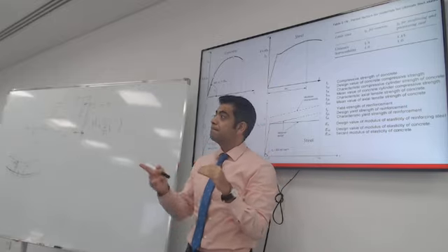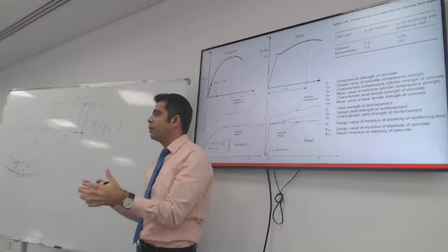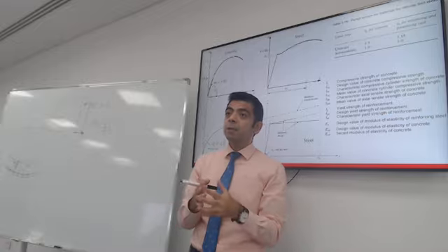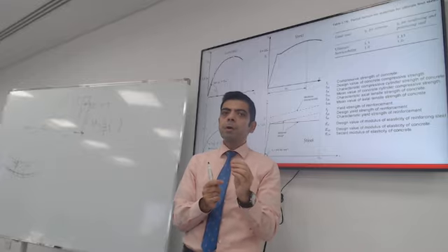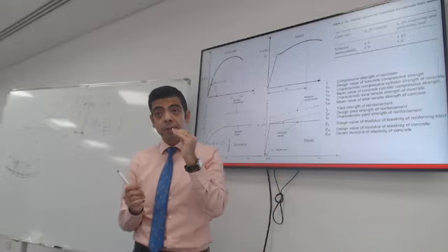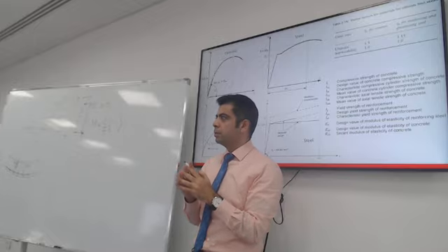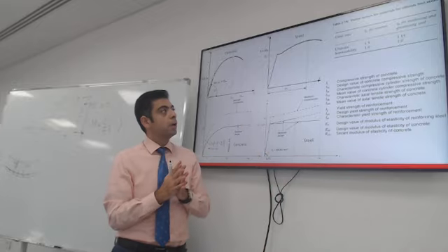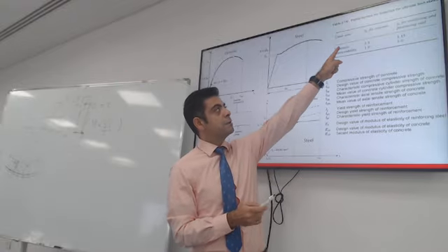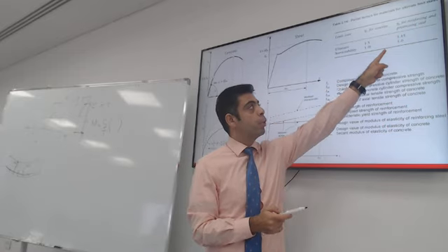Variation in manufacturing. Because concrete is manufactured mostly on site or in a concrete mix plant, which most probably will not have the tools or the possibility to have quality control as much as the factory that will produce steel. So I need you to know 2 factors very important. The factor of safety for concrete material is 1.5, for steel is 1.15.